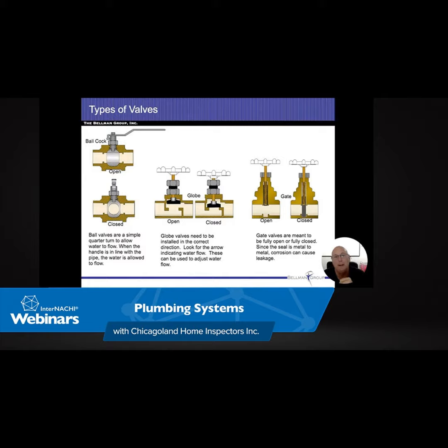So as long as the hot water is leaving through the top and the cold water is entering at the bottom, we'll be able to use the vast majority of the hot water in that tank. It won't churn, it won't mix, it won't try to equalize out as long as that water is flowing and we're taking a shower. So we'll get the best use out of it that way.